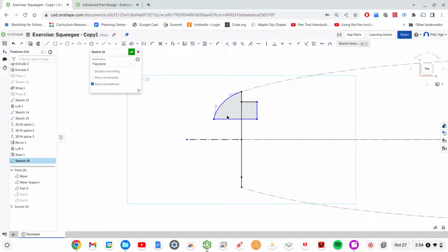Alright, now I'm going to do some dimensioning and creating some constraints here. So these handles need to be able to have constraints and dimensions applied to them. So I need to draw a construction line that's attached to it. So I'm going to enable construction and grab the line tool, and then add a construction line to both of my handles.